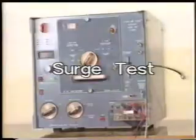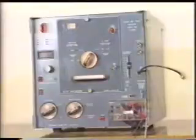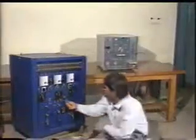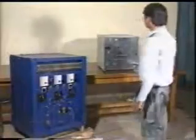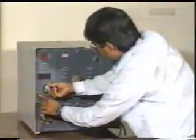Surge test. This test is conducted to determine the effect of lightning or switching surge on the equipment. The equipment is given AC main supply through the surge tester. The equipment under test is switched on for performing the test in on condition. The surge can be either positive or negative.